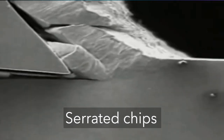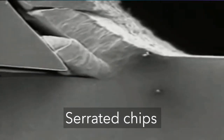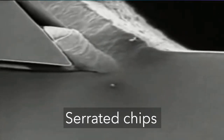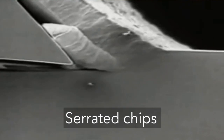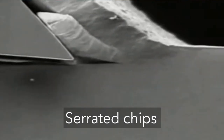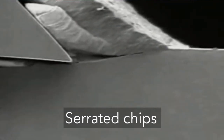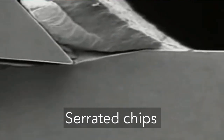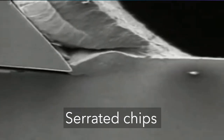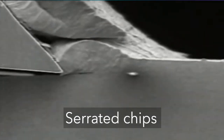This fourth type of chip is most closely associated with certain difficult-to-machine metals such as titanium alloys or nickel-based alloys, especially when they are machined at higher cutting speeds. However, the phenomenon is also found with more common work metals like steel when they are cut at high speed.